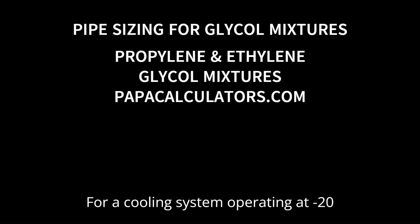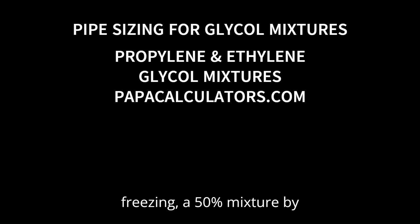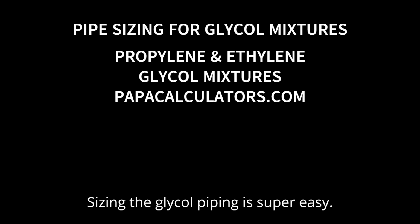For example, for a cooling system operating at -20 degrees Fahrenheit, that is below freezing, a 50% mixture by volume is needed. I have a tutorial for determining the glycol freezing point on YouTube. Sizing the glycol piping is super easy.